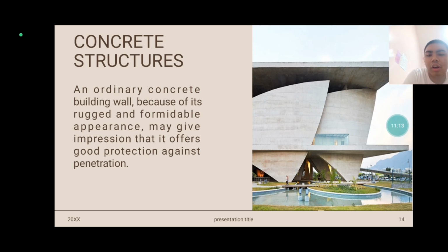But the standard poured concrete or concrete block wall is utilized to support the structural loads of the building, used to enclose spaces between the load bearing walls, but it is normally not designed to prevent or delay penetration. Concrete walls that are less than 6 inches thick are vulnerable to penetration by hand tools and small amounts of explosives.